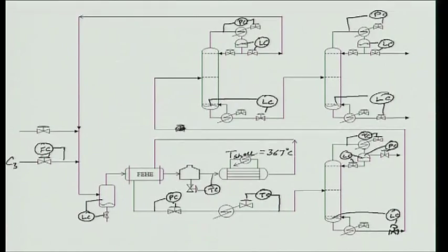Okay. How many valves are left now? I am left with this valve, that valve, 1, 2, 3, 4, 5. I am left with 5 valves. Okay. The total benzene flow reflects the inventory of the benzene, and therefore, I do a total benzene flow control inside the process, and this makes sure that I do not put in too much benzene or too little benzene. I put exactly the amount of benzene that is required in order to eat up the C3 that is being fed. Okay.